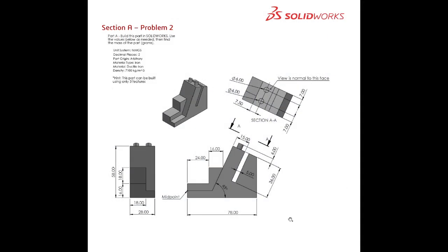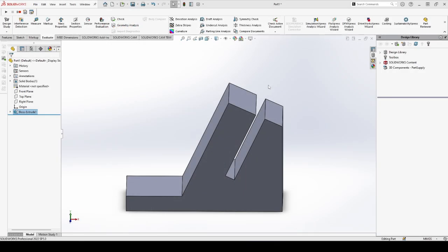The next step, you could do either those two protrusions on the top next, or the two steps next, as they're both unrelated to each other. I'm going to choose to do the two steps next, but it really doesn't matter which one you do first. So doing the two steps next, we know that the two steps are flush with the back face of our part. So that's where we're going to put our sketch, just for simplicity's sake. You could put it on the front, but then it's an extra step to define where from and where to. So let's go ahead and do that now.